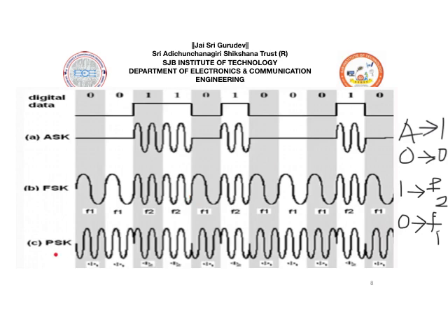Now, moving on to the third type, PSK. In PSK, as we discussed here, for binary value 1, there is no phase shift, we say it as 0 radians. For binary value 0, there is a phase shift of pi radians. This is what we discussed. Accordingly, if we take this digital data and analyze the final waveform of PSK here, as you can see there is a 0 here. So, whenever there is a 0, there is a pi radians phase shift. That is why the waveform is starting in the negative region, having a 180 degree phase shift.